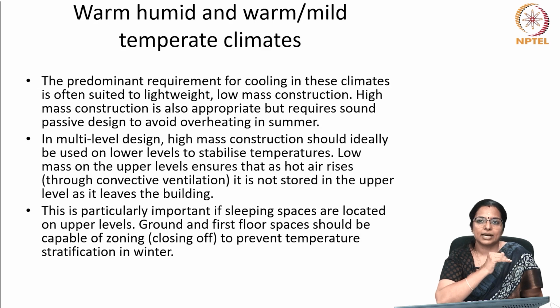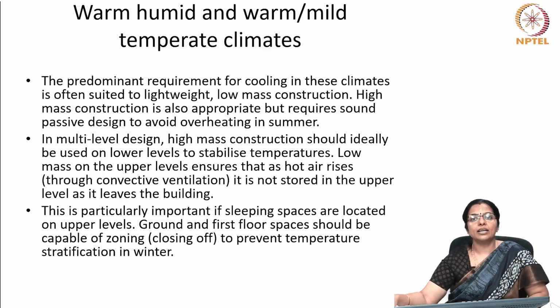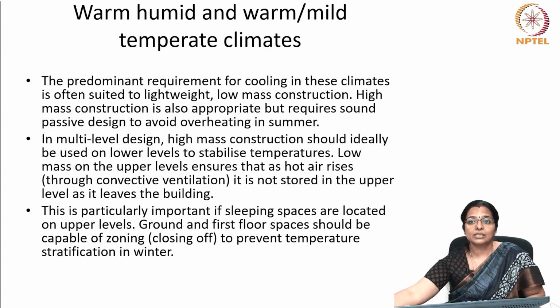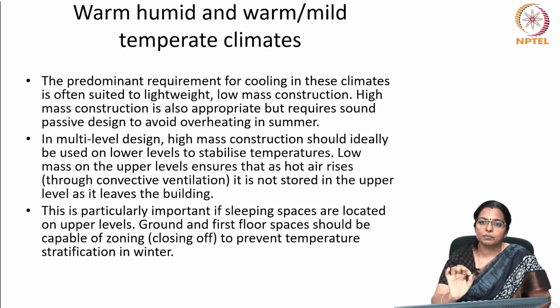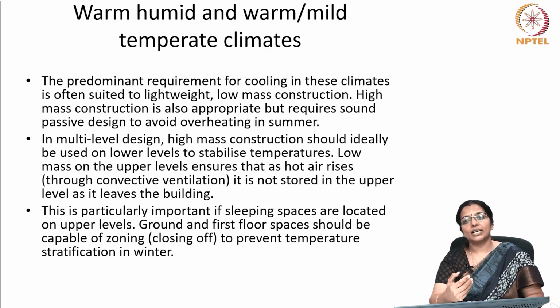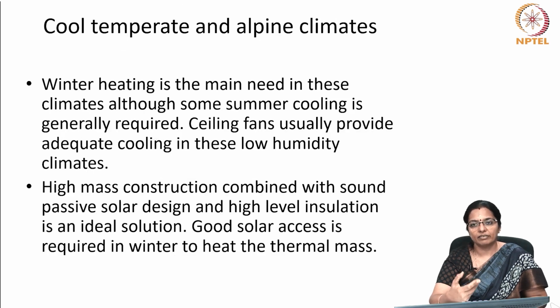In multi-level design, high mass construction should ideally be used on lower levels to stabilize temperatures. Low mass on the upper levels ensures that as hot air rises through convective ventilation, it is not stored in the upper levels as it leaves the building. This is particularly important if sleeping spaces are located on upper levels. Ground and first floor spaces should be capable of zoning or closing off to prevent temperature stratification in winter.